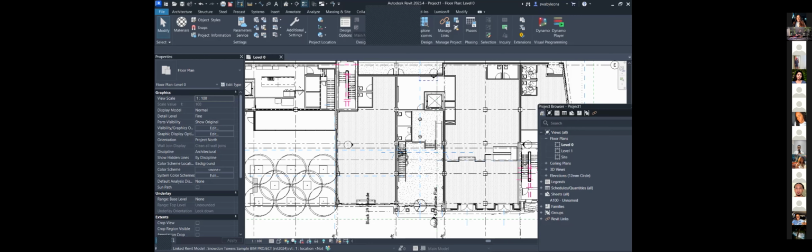So you draw it once and use external references to bring it in, duplicate and mirror, duplicate and mirror. Linking is one of the major uses in the architectural industry. Housing drives most of the industry, perhaps the majority of projects you will work on, and housing has repeating elements.